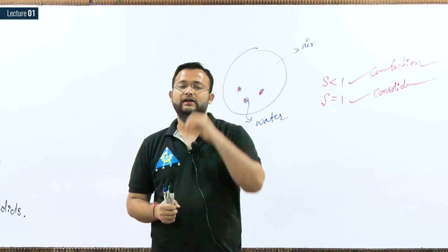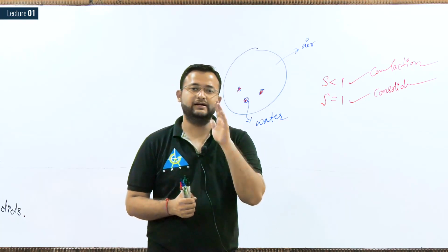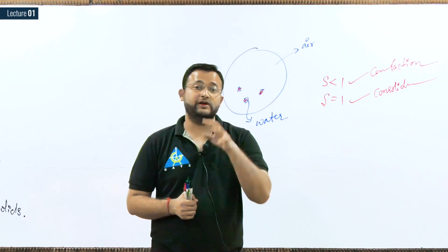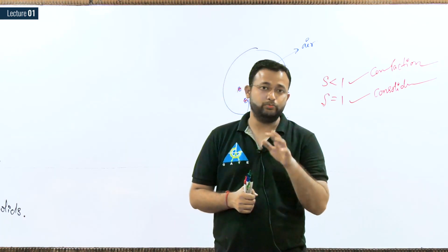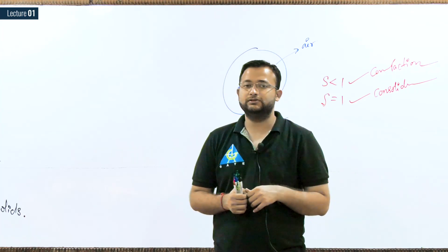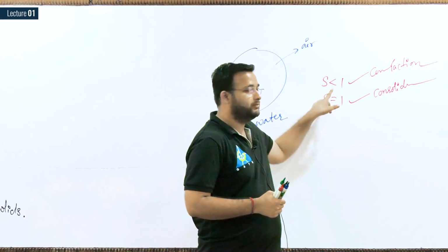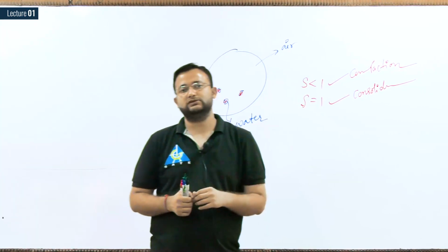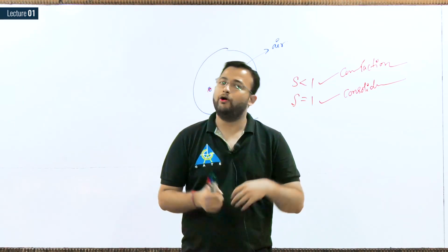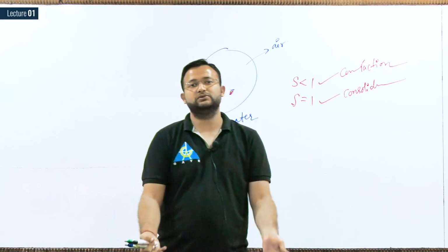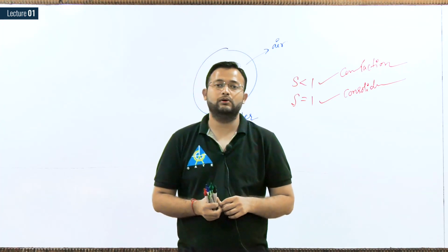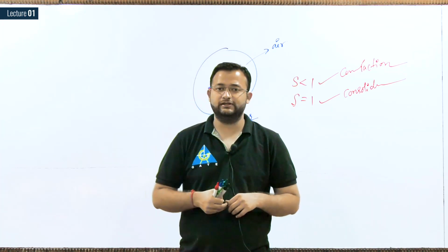So I can say in your plot the degree of saturation of your soil is 1, because when you purchased the new plot, the degree of saturation was less than 1, since air was present and water was present. But you have removed the air. Now only water is present, means the degree of saturation is 1. Now the process we can perform is known as consolidation.